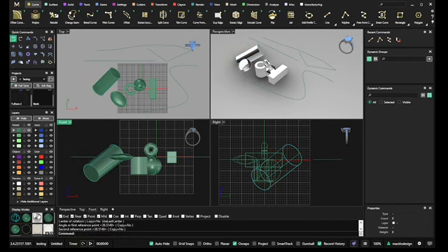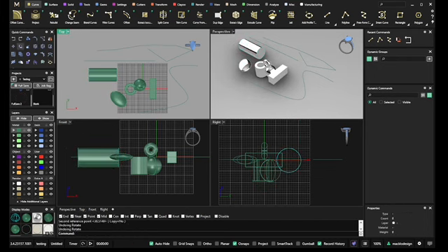All right, I'm going to back up because I wanted to go over that again. We talked about the rotate before. So what I did to rotate that was I left clicked on rotate and I clicked the item, select objects to rotate. It says right down here in your command line, press enter when done. And then it wants to know the center of the rotation. I can pick anywhere. It doesn't matter. I can pick on the object. I can pick over here.